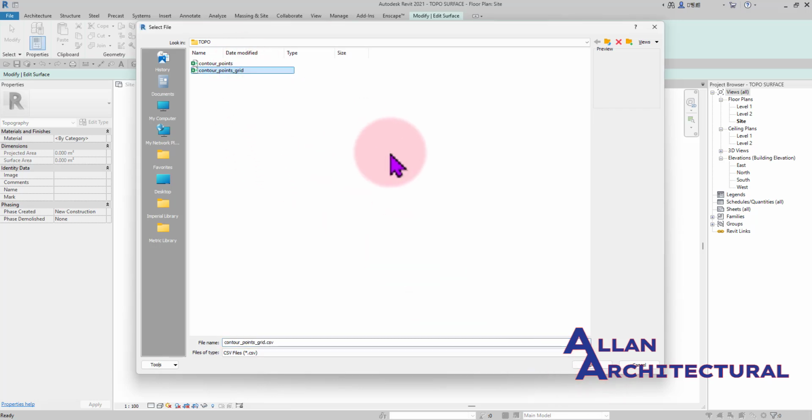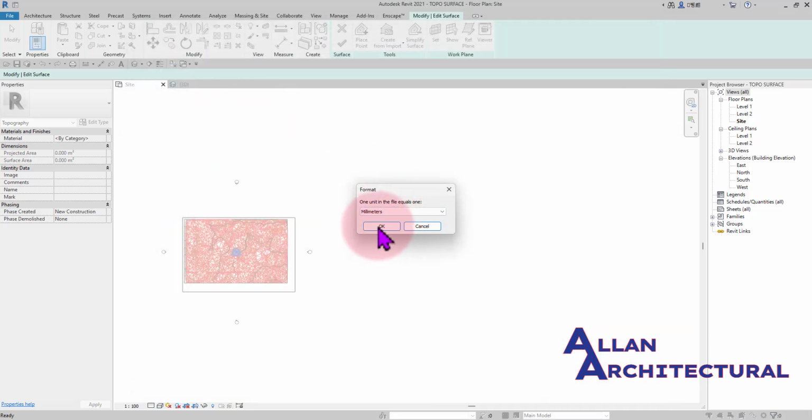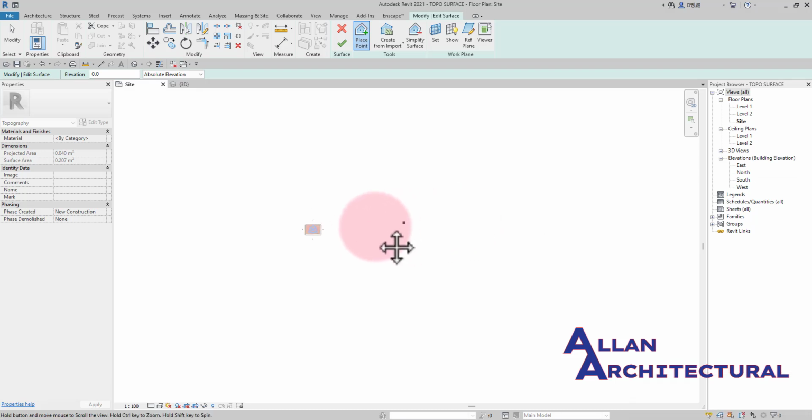And if it still gives me that weird shape in there, then it means that my point file is actually way beyond. It wasn't designed properly. I got this online, and I do not have a sample file to actually show you guys, but we are going to find a way where we can actually generate a points file from AutoCAD, and then we bring it into the Revit software. So let me just click on this, and let me change this to millimeters. Let me see what it's going to give me, and it's not going to give me anything. So that means that my points in there were way too small. I need to bring them in meters to actually see that point file. It's way too small in there.